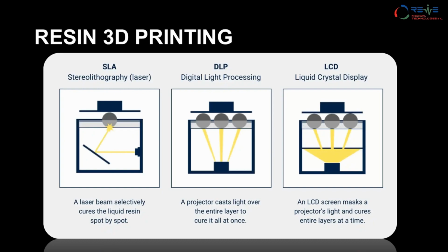The same principle would happen. The third technology that came into place was direct light processing. In this, they added a projector, and the light source would remain fixed, and the projector would move, and that would angle in the light. All three technologies have their advantages and disadvantages primarily, but LCD is the most cost effective out of the two. SLA is the most accurate out of the two, and DLP is the most cost effective in terms of usability.